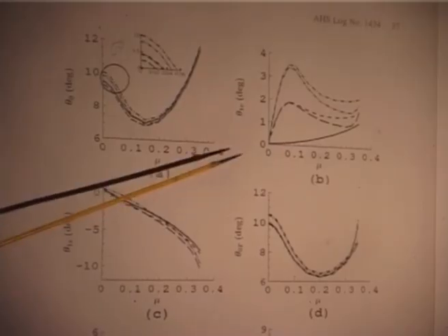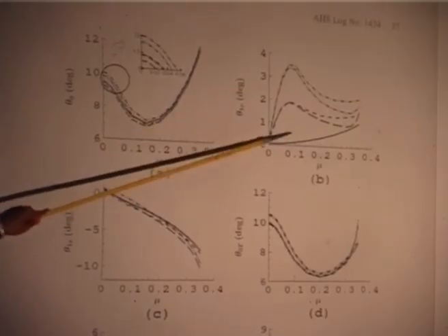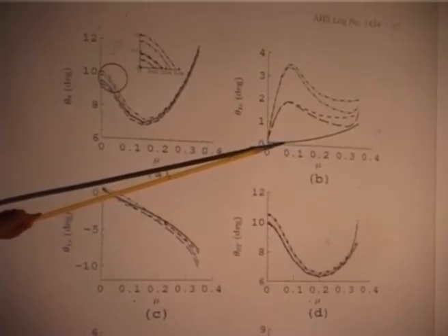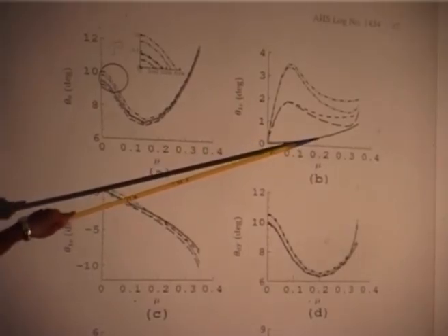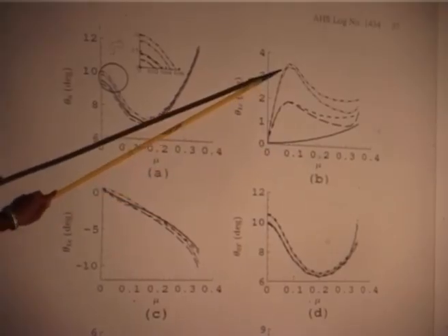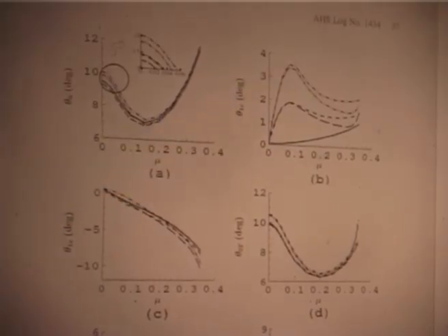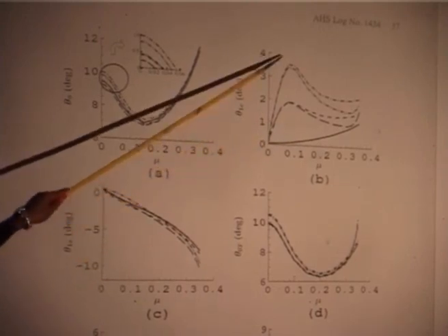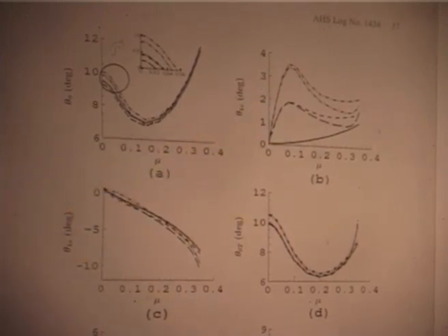With the different aerodynamic models, I am getting different curves. This is the uniform inflow curve, the lowest, the continuous line, and for these I have included a dynamic stall model and dynamic wake, some additional more complex models. You see they change drastically, okay, just in equilibrium.